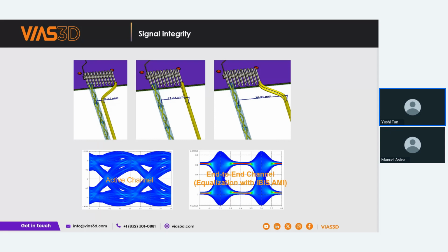So now the interconnects and also the connectors can be modeled and simulated in full 3D to capture all the effects. Like I said, twisted pairs, splaying, similar to kinks and bends, all have some kind of effect on the signal integrity. So higher bandwidth, higher frequency applications require pretty tight tolerances on signal integrity. And automotive CAN buses, we have a specific set of rules to follow.